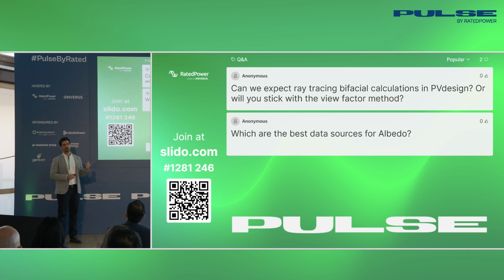The automatic albedo sources we have, which are MODIS and NASA Power, they are really good because they are publicly available worldwide data sets, free of charge, right? But I would expect SolarGIS data to be better than that, even if, I think, SolarGIS is actually using MODIS data as well, but they do additional processing over that, which may improve the quality of the data. And also, at the very least, they can tell you about uncertainties, which is not something that is easy to find for the public sources.